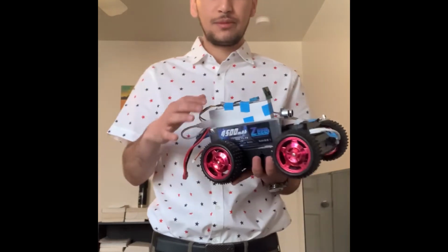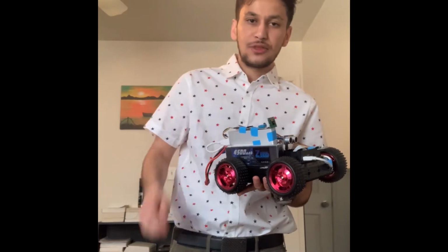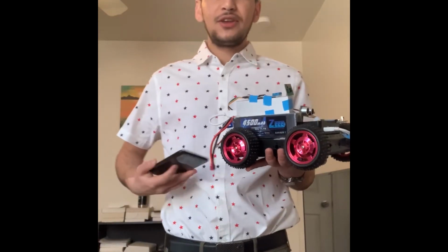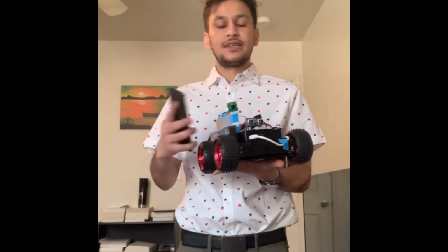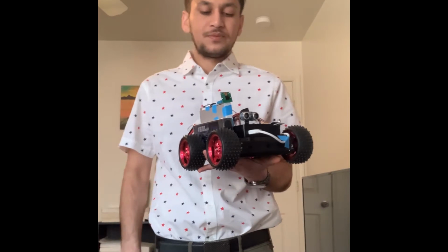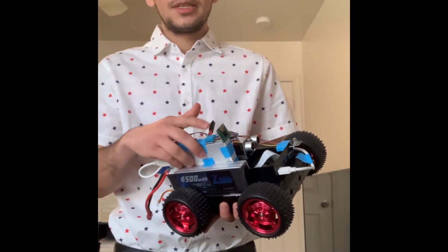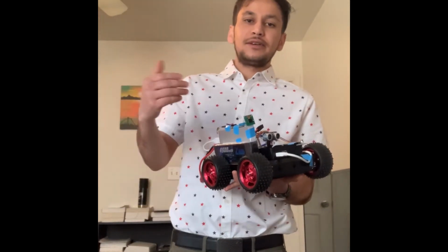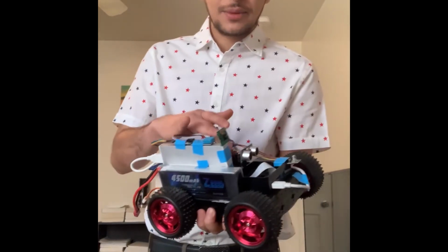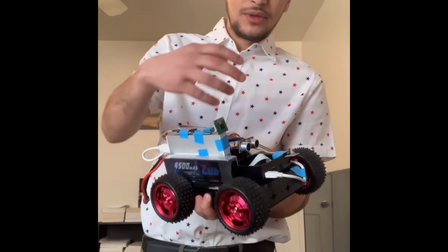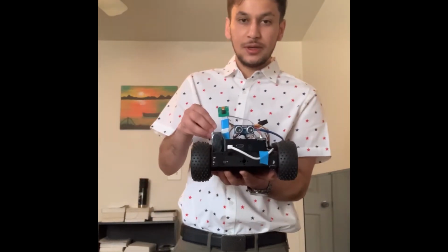The third input sensor is a Bluetooth module. This Bluetooth module is used to establish communication between the NanoRobot and this Android app we developed for our project. So this Android app is used to navigate and change the state function of this car. The next input sensor is the temperature and humidity sensor, and it can send the temperature and humidity data of the incident. And there is also one motor driver, an L298N driver inside this, which is powering all these 4 motors, and it is driving this robot.